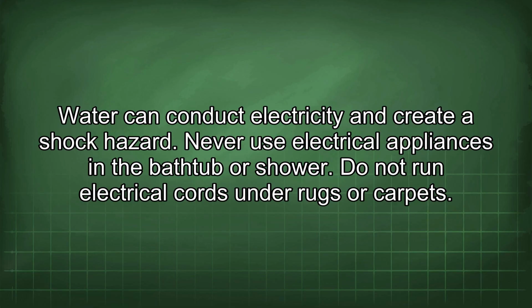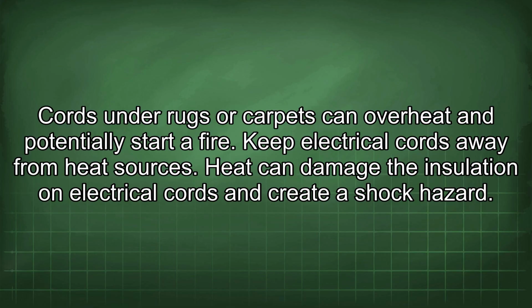Do not run electrical cords under rugs or carpets. Cords under rugs or carpets can overheat and potentially start a fire. Keep electrical cords away from heat sources. Heat can damage the insulation on electrical cords and create a shock hazard.